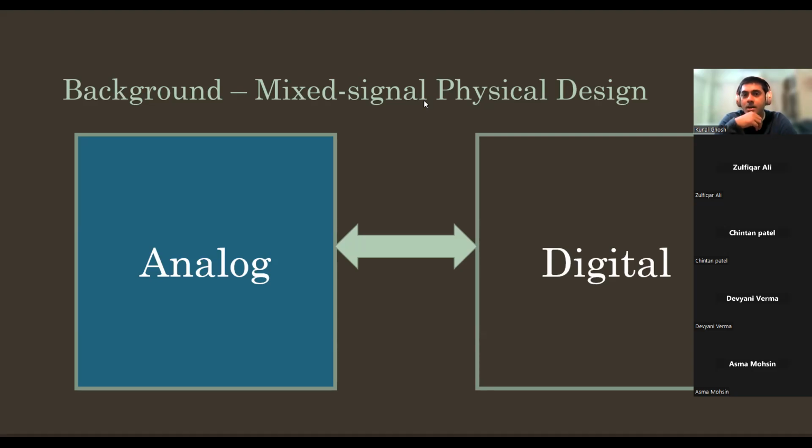Clock is generated from a crystal that enters the IOs, and internally it gets multiplied by a PLL, again an analog block. For any chip in the whole world, and especially for students, if you think of physical design as mixed signal physical design rather than only digital physical design, that will give you better scope of jobs or attention in this particular market.